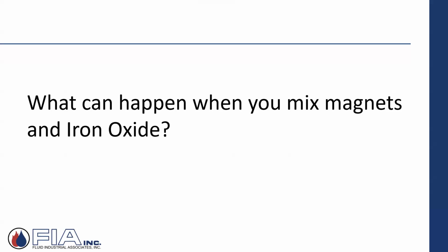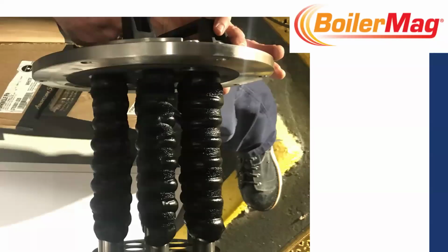Just one quick comment, as a general statement. When you get into this technology and they have magnets and you're attaching them to systems, sometimes they're brand new systems, everything's spotless clean, all copper pipe. Then other times, in the real world, it's maybe some existing steel pipe with a little iron oxide out in the field. And all of a sudden you're putting this big magnet in line, and what can happen is you can collect the iron oxide and it can damage these pumps. So the third leg of the stool, after high efficiency boilers and high efficiency pumps, is to put some type of magnetic filter in line. Just something to be aware of.